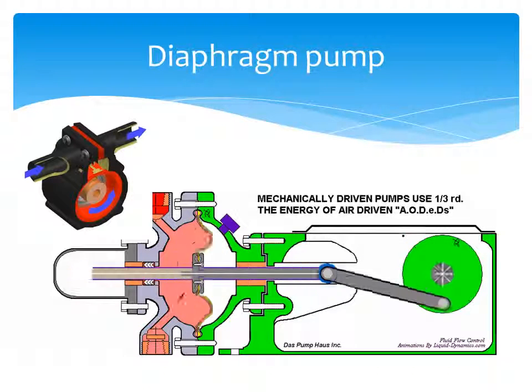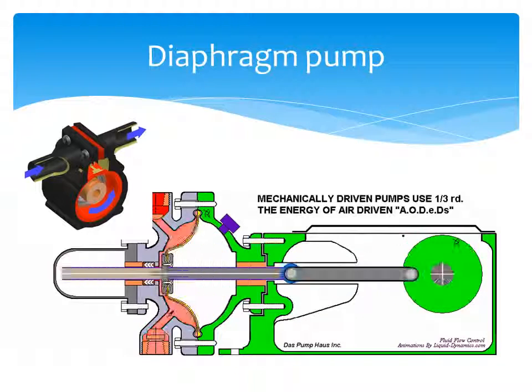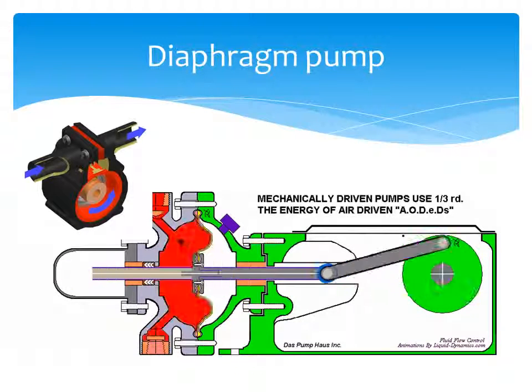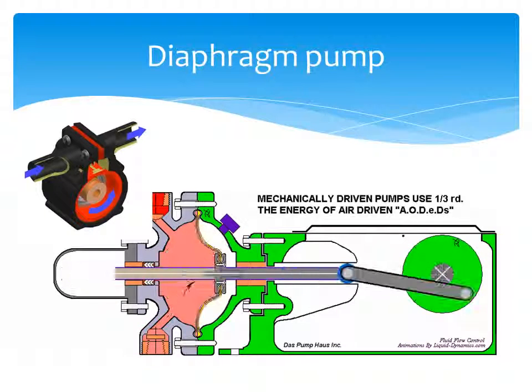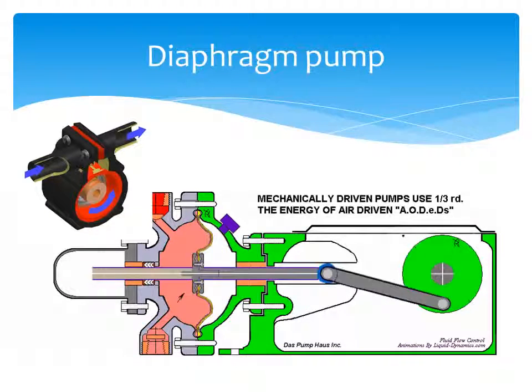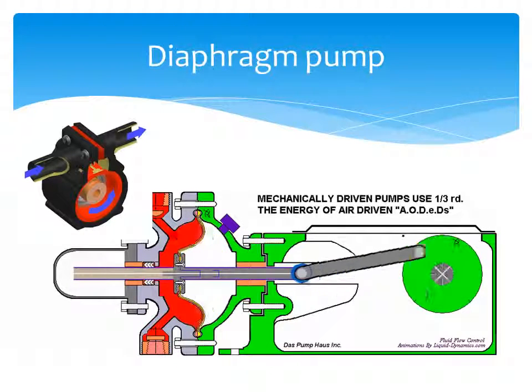When the chamber pressure later increases from decreased volume, the diaphragm moving down, the fluid previously drawn in is forced out. Finally, the diaphragm moving up once again draws fluid into the chamber, completing the cycle. This action is similar to that of the cylinder in an internal combustion engine.